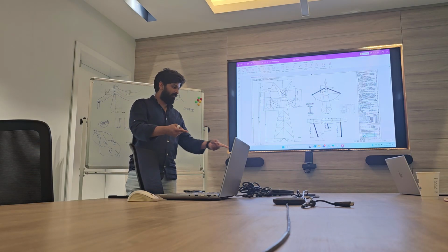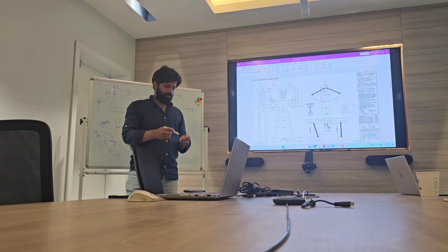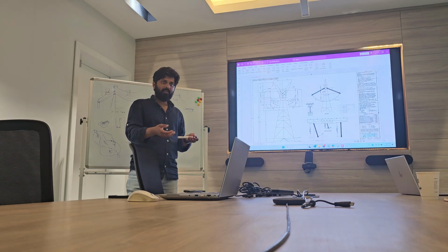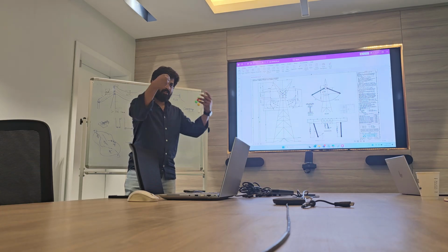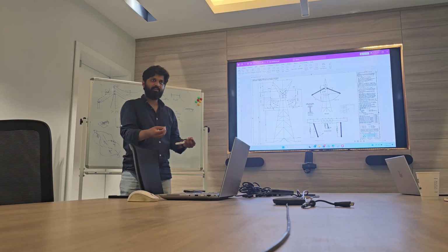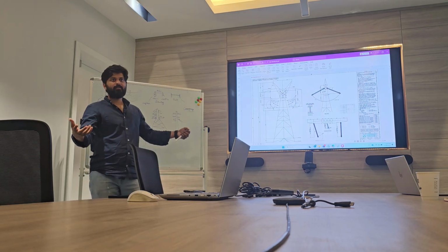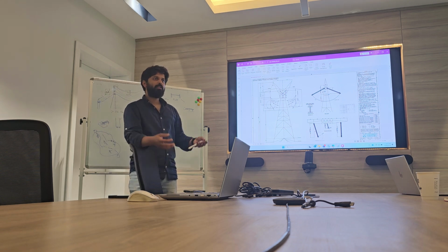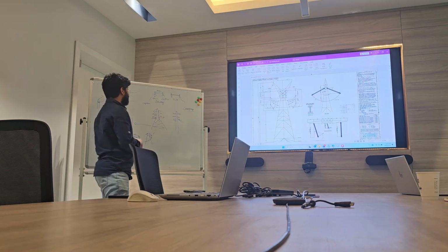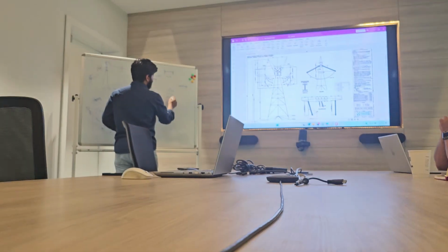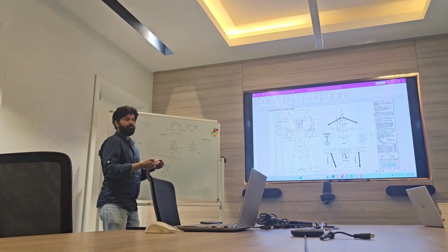Now, if I catch this wire from this side of the table to that side of the table, and nothing is catching it there and here, and I hang it, after a few days everything will come down. You understand my point? Because of its weight, with nothing holding it, the complete wire will come down. So that holding point is a tension insulator. We'll put the conductor here, clamp it, and hold it.